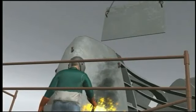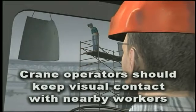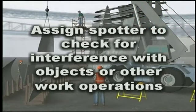The welder was not aware that the crane had started to swing over his work area. Educate all workers of the hazards around working cranes. Crane operators should keep visual contact with nearby workers. Assign a spotter on the ground to make sure the crane will not interfere with other objects or other work operations.